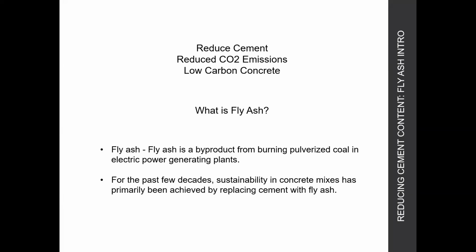Sure. So to talk about fly ash, another key ingredient commonly seen in concrete, it is a byproduct from burning pulverized coal in electric power generating plants. For the past few decades, pretty much my whole career, sustainable concrete has been viewed as basically how much cement can you replace with fly ash. It serves a similar purpose as a cementitious material, and actually has some benefits that can help the concrete durability. It has some other drawbacks, but primarily over the past few decades, fly ash replacement has been the main means of reducing the amount of cement and therefore the carbon emissions in concrete.